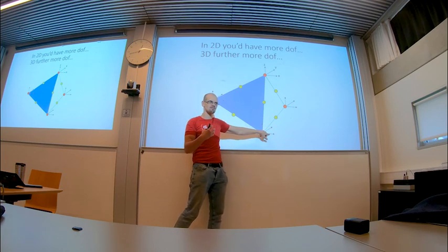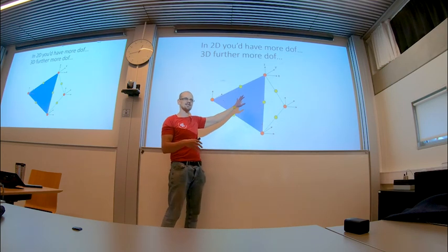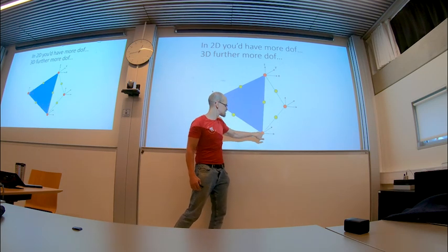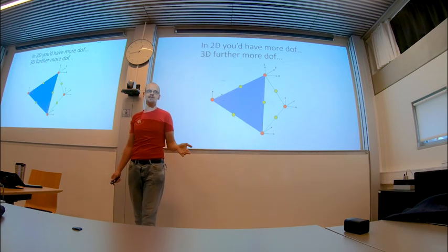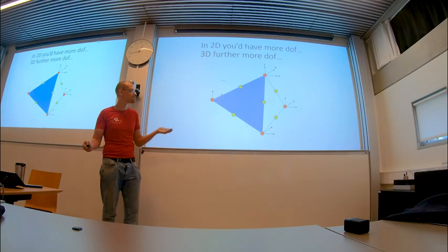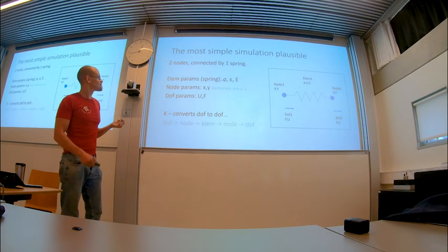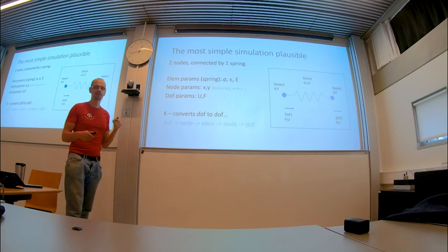Or you can use some advanced field equations to distribute it through this field of imaginary displacements, imaginary work functions. So you move it and then get some reaction force from displacement of 1, and then measure the rest of them. And that's how you can build elements. You can do it by physical measurements, you can do it theoretically, both work. And then you have some number of parameters controlling the stiffness, and this is all elasticity so far.